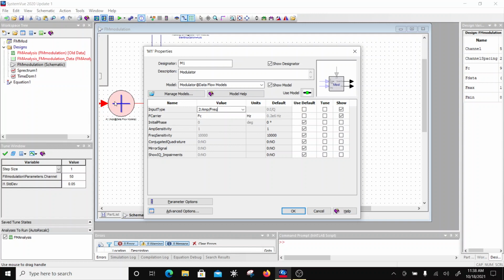Now the amplitude of the input signal is plus minus 1, right? So that's fine, but then you have to specify the modulation depth. So how many kilohertz per volt, kind of thing. If I put here 75E3, that many hertz per volt. So if I go plus 1, it will give me 75 kilohertz, and if I go minus 1, it is going to give me minus 75.